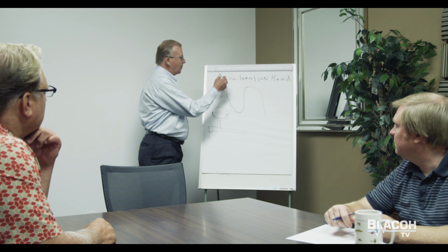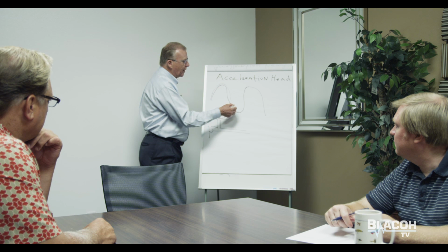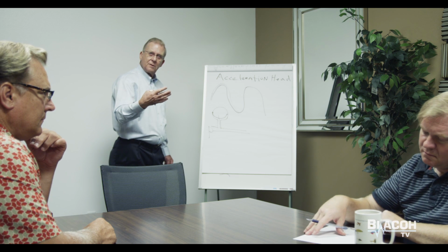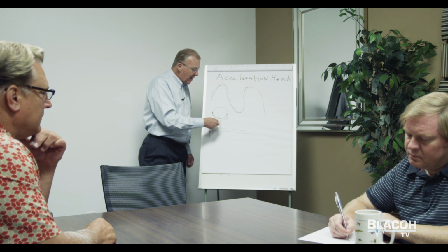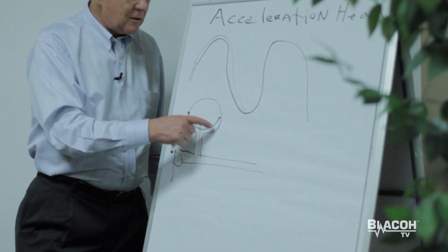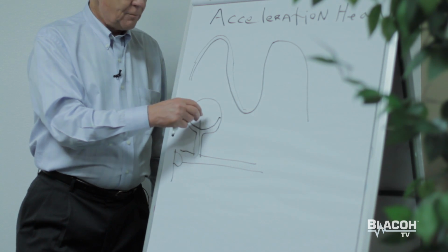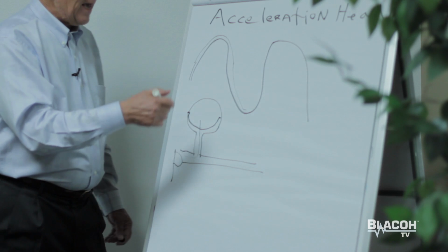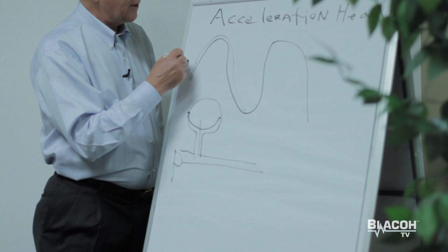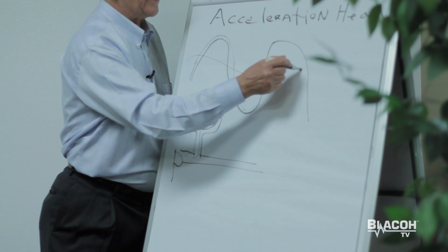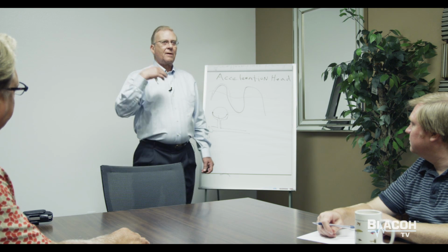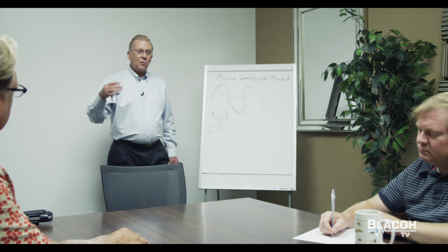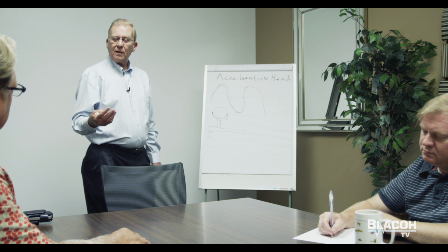But when the pump reaches its peak and starts to stop, or at the end of its stroke, and retract to recharge, now the pressure in the dampener is higher than the system pressure, so this accumulated or stored liquid is pushed back into the system by the stored energy that the pump provided, and it evens this flow so that we don't have a peak or a valley, but we tend to have near steady state flow like that produced by a centrifugal. Well, when the system is in near steady state flow, we are not using excessive energy, okay?